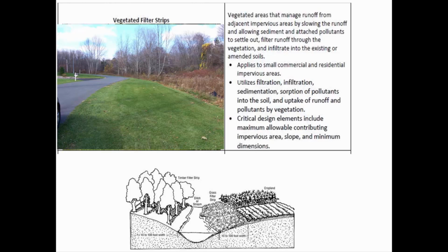When you've got a depth of water, it can move with less resistance through that channel than if it's flowing as a sheet. So you just think, what kinds of flows are slow? Sheet flow. What's going to improve infiltration? Vegetation. And so that's the idea of a filter strip. And this is showing it next to a roadway. There are places where they do the same thing in a parking lot, where just putting in patches of grass in a spot where peak cars aren't going to be parking can have an enormously positive impact. And also it improves the water quality as well.